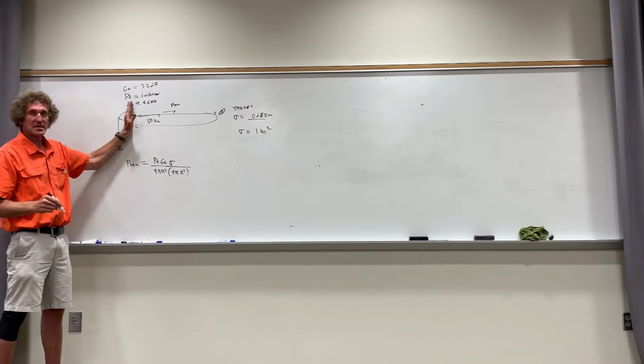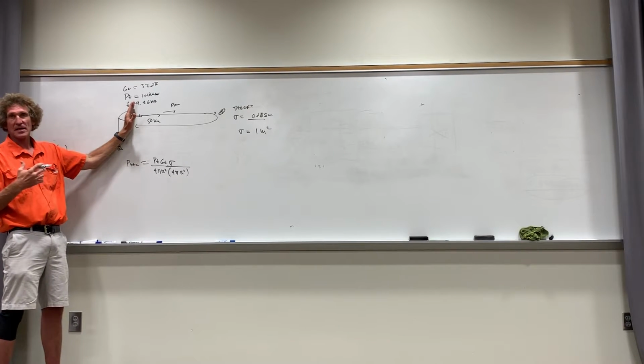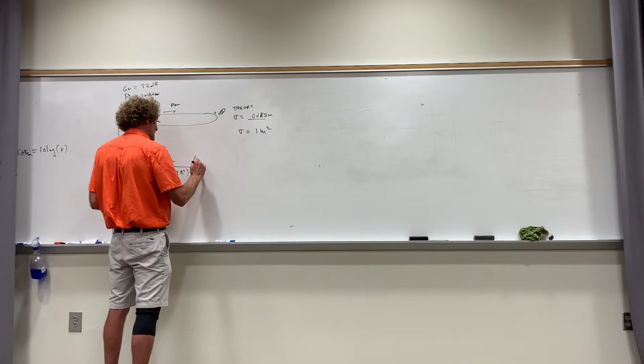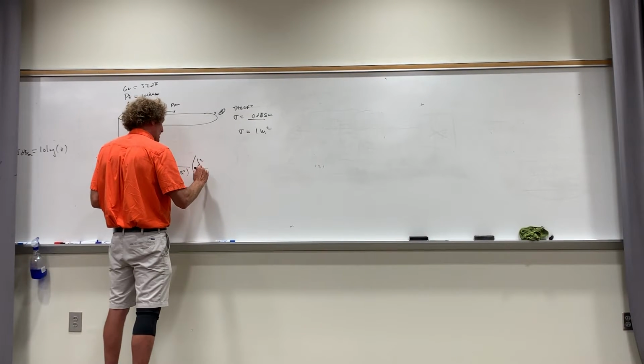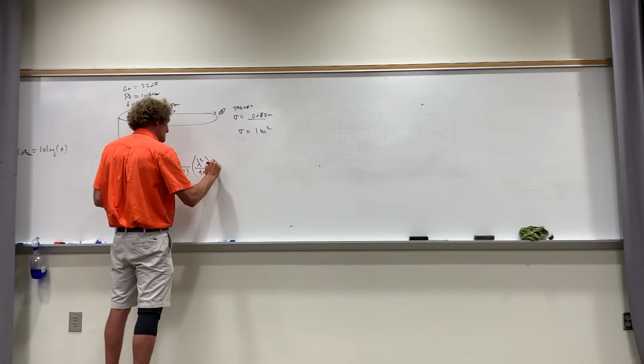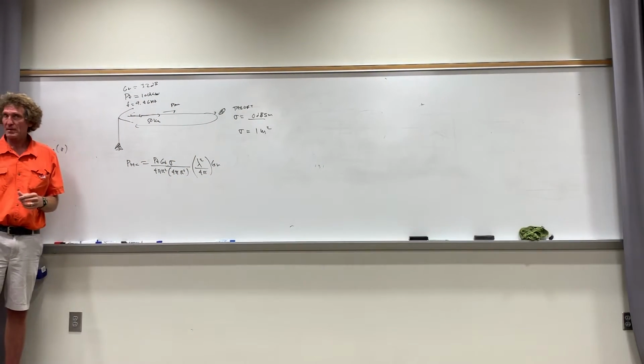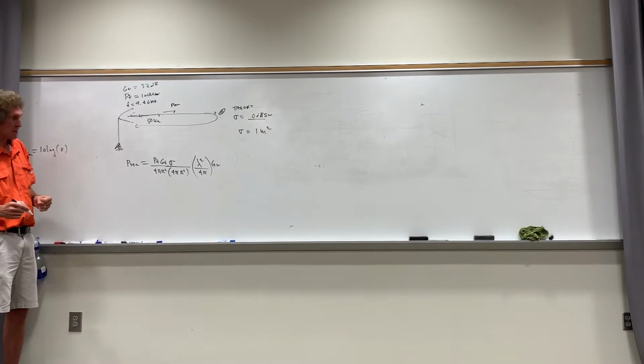Then it strikes this antenna, and the antenna catches it. It's times the aperture, the electrical area of the antenna, right? And you remember what that is? That's lambda squared over 4 pi times the gain of the receiver. And that would be P received. Y'all remember this? The way I did it before? Class. So now we just stick in the numbers here.